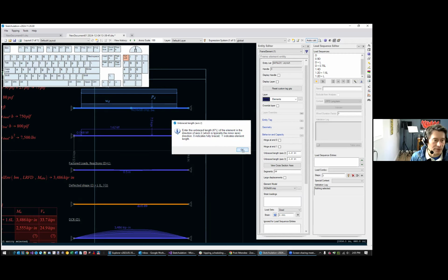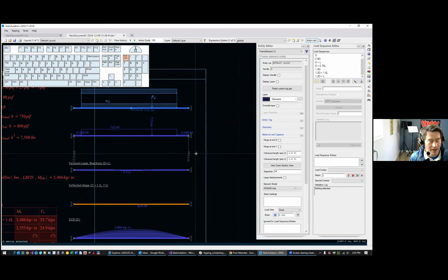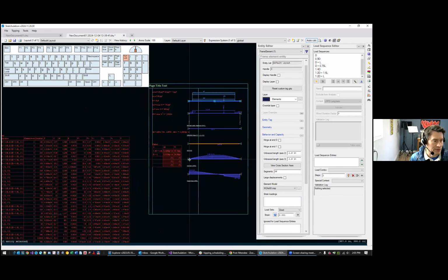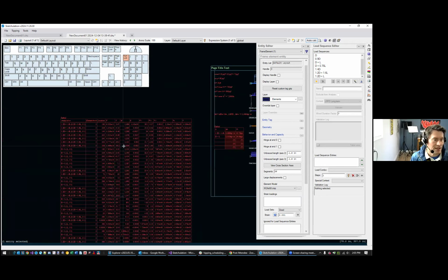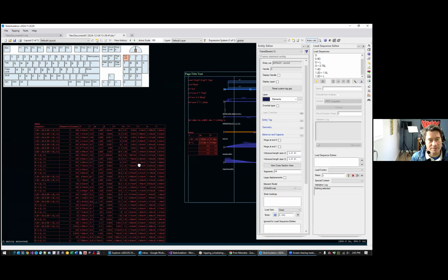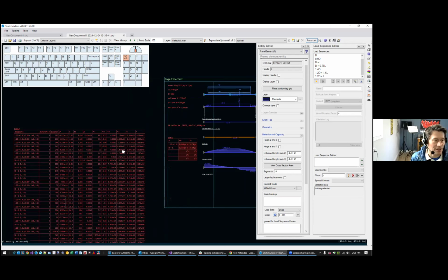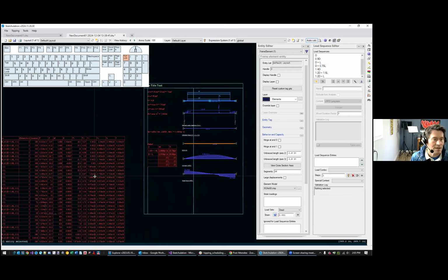The reason that I brought that up is because if you look at the actual DCR checks, there are lots of things going on that take into account combined loading, slenderness checks, and all kinds of things. And so in the past, I've been reticent to provide this kind of table information that would then be used for design, because it'll always be less complete than what we're doing internally. It's nice for a check, and I use that from time to time to check. But I would just want to provide a word of caution on that.